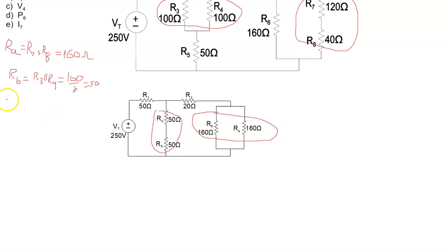So I said that our C is equal to our 6 in parallel with our A, and you'll notice again that this one has been designed to be easy to reduce because we have 2 equal resistors in parallel, and so we'll take that 160 divide by 2 and come up with 80 ohms for that branch.